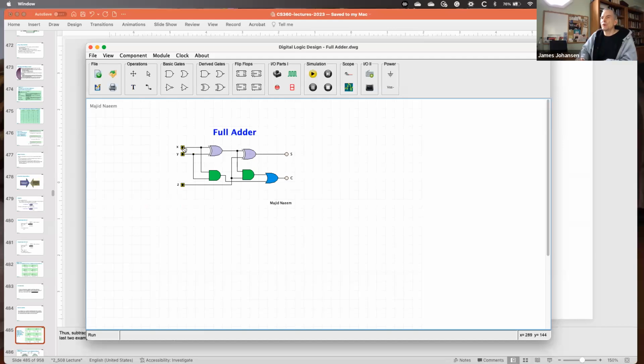And so this is operational. If I just click one of those, it'll give the output as 1. If I deselect that one and select the other one, we also get 1. If they're both on, then we see there's a carryover that we need to be concerned about. Okay, let's give another situation. Let's say we have input that we're carrying from another stage. That automatically says that we have this. So if I have another one, it says that I have to deal with that.